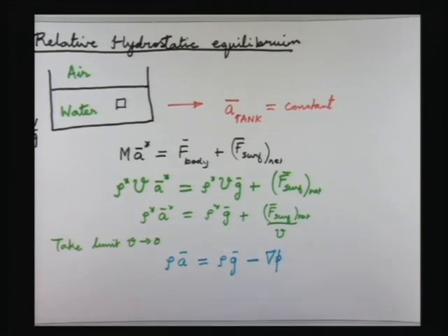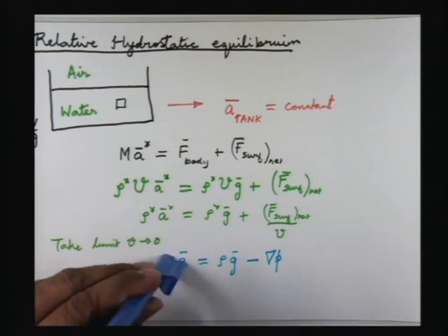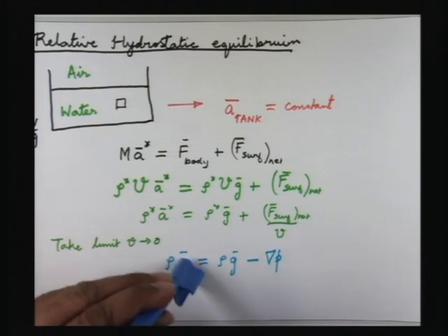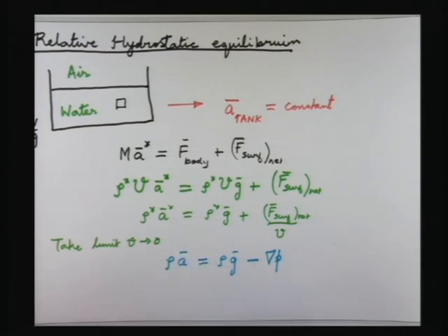So when we looked at the basic equation of hydrostatics, the left hand side was 0. We had rho g minus grad P equal to the 0 vector. Now we have this additional term, and if you want, you can write A as the material derivative of V, which was covered this morning, and that will give you the equations of motion for an inviscid fluid. Now we are considering a case where after this fluid surface oscillates, the oscillations will die out.